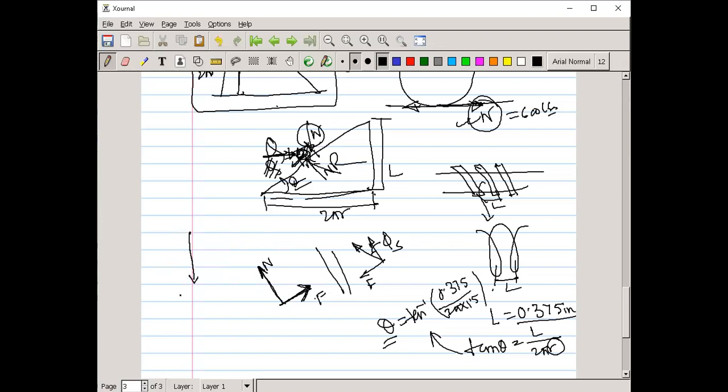The force triangle, that this is your W, downward direction, which is given 6,600 pound, right? This is your resultant, and this resultant creates an angle with respect to normal, that is phi s, and the normal creates an angle with respect to vertical, theta.